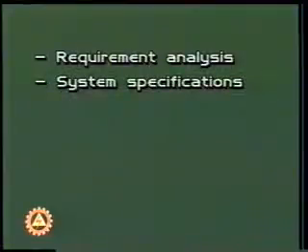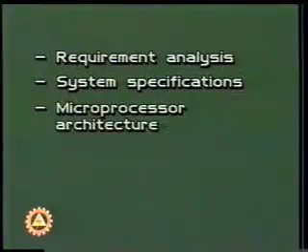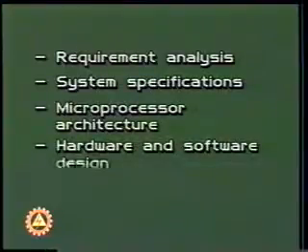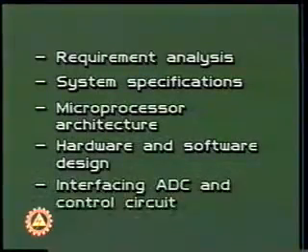The design process of the system brought together all the concepts of requirement analysis, system specifications, microprocessor architecture, hardware and software design, interfacing analog to digital converter and control circuit with the microprocessor 8085. And the case study included debug and test procedures besides the burn-in tests for proper operation of the system as per user requirements.